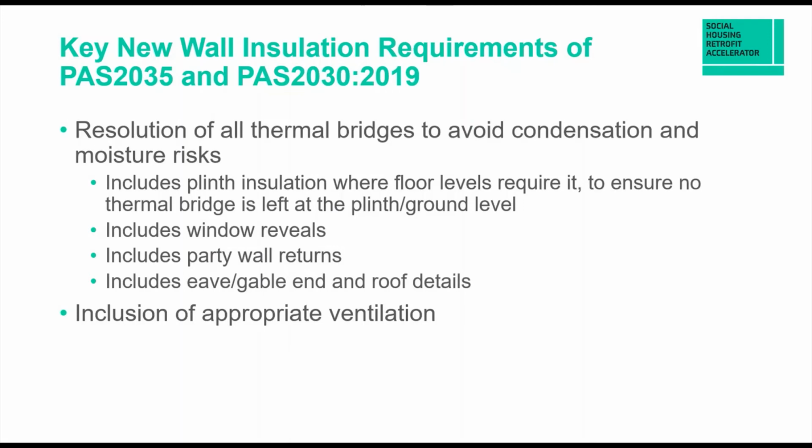And depending on where exactly the floor and the ground is in relation to that, sometimes you end up with a big stonking thermal bridge right at the bottom of the wall. And the plinth insulation is required to resolve that, such that we make sure that we don't have a thermal bridge all the way around the perimeter of the bottom of the property.